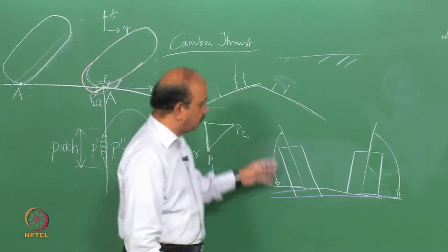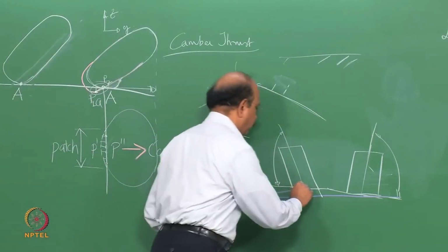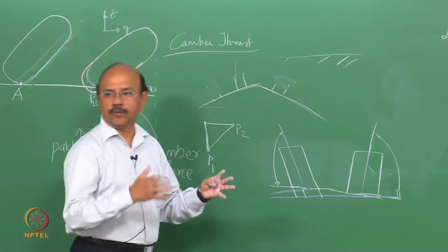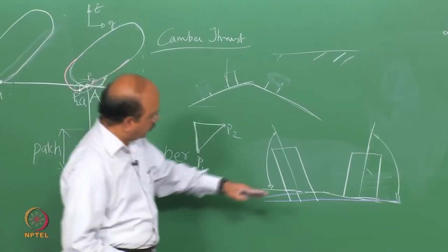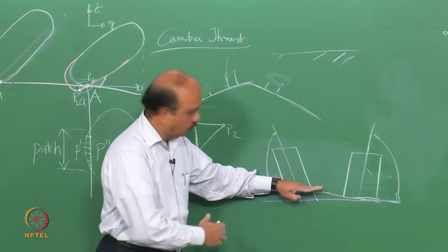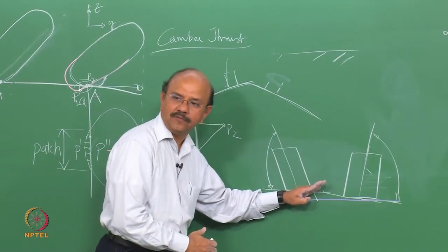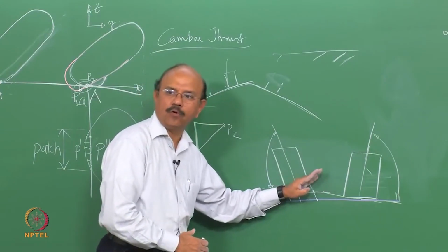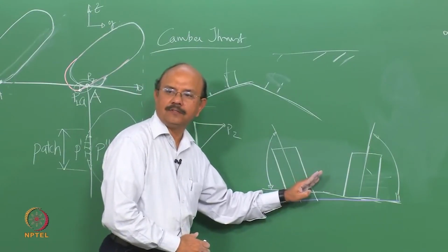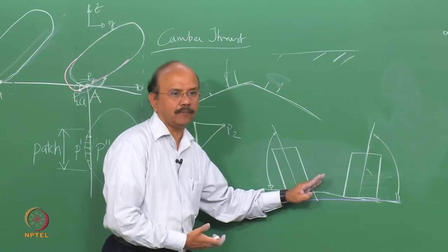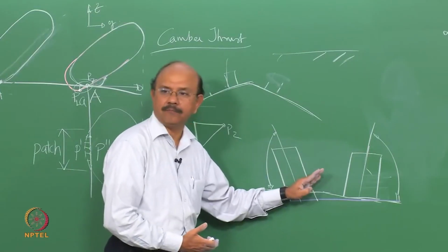So there are two angles now. This is how the tire is now going to sit, right? So in other words, what was straight here, you have rotated in this direction, which means that you have made it more towards zero camber, or reduced the camber.